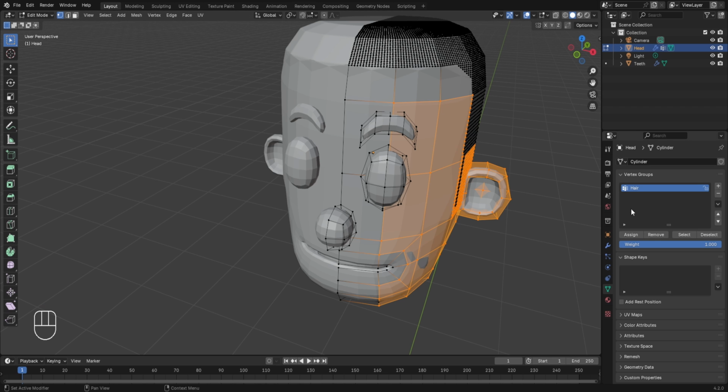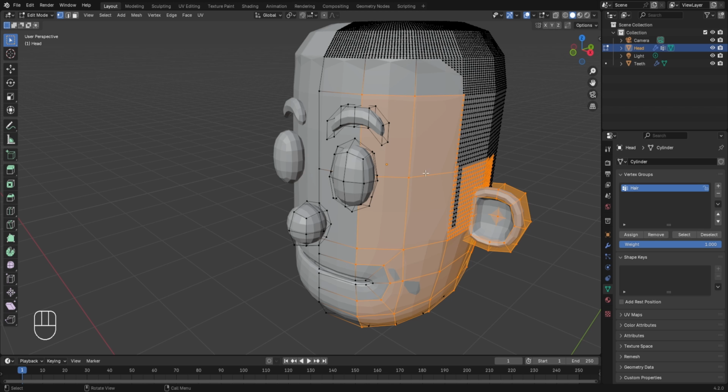Also, one more thing that I should explain to you in the edit mode is that you might be thinking that while removing the vertices, we have selected all these unwanted vertices which are not related to the hair particles. But as I told you before, when you are removing the vertices in a vertex group, it will not consider these vertices which were already not part of the vertex group. It will only consider those selected vertices that were already there in the vertex group.